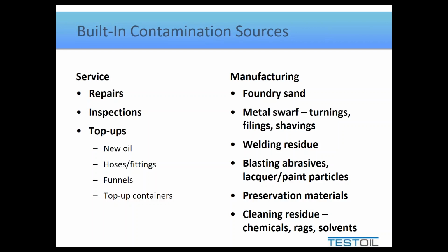And anytime we add oil, what if we're using dirty components? A dirty pail, a dirty funnel. Sometimes you'll see that people have hydraulic hoses, but they let them dangle on the ground or otherwise get contaminated. So when they connect the fittings together, they're in fact pushing contamination into the oil.